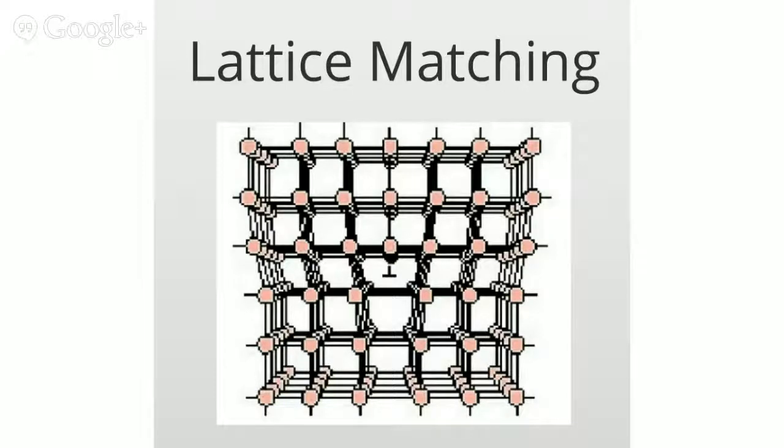So you end up with a little bit of a defect. You have 1, 2, 3, 4, 5, 6 germanium atoms. Up here you have 1, 2, 3, 4, 5, 6, 7 indium gallium phosphide atoms, and they alternate. And you can see, because of that, you get this bending. You have the stress, and you have some defects. And this is where the electron hole pairs get trapped. You want to avoid this as much as possible. And the way to avoid this is by doing a very slow, high vacuum epitaxial growth. And that makes it slow, expensive, still complicated, not terribly useful for low cost.